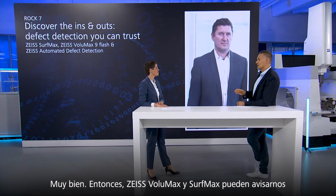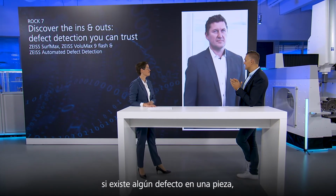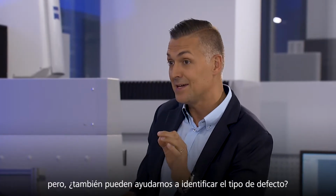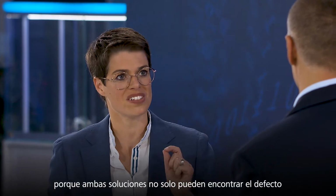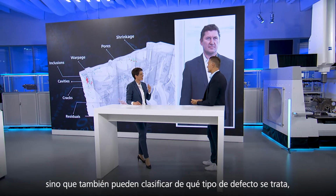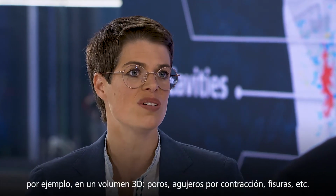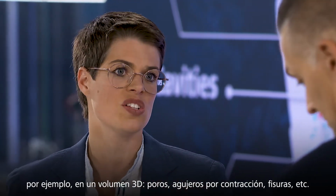All right, so Zeiss Volumex and the SurfMax can let you know if there are any defects on a part. But can they also help you in identifying the type of defect? Well, you hit on a very important point, because both solutions can not only find the defects, but they can classify what type of defect it is. As in a 3D volume, for example, pores, shrinkage holes, cracks, and so on.